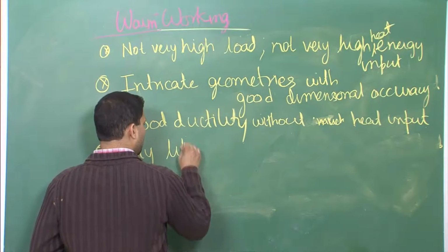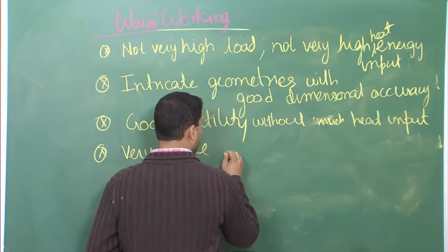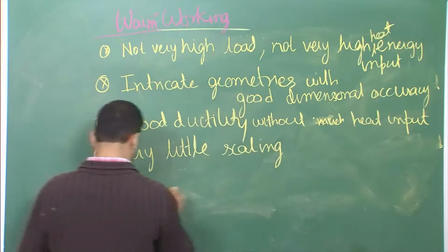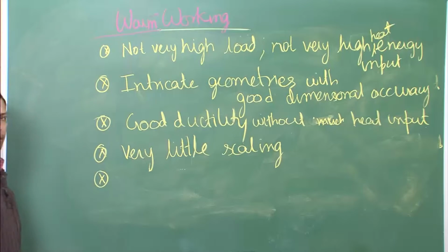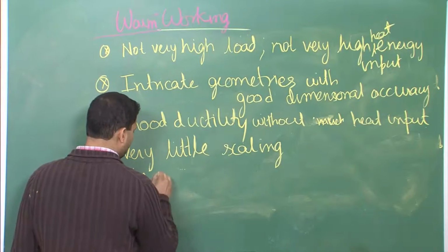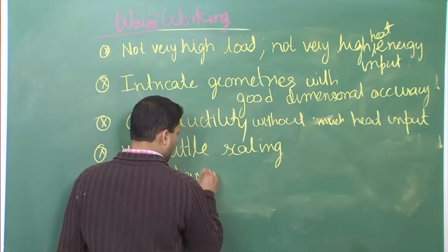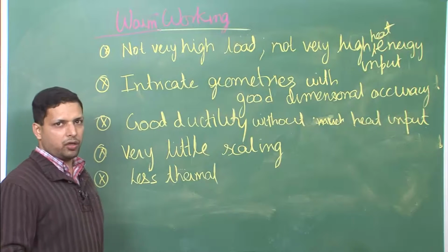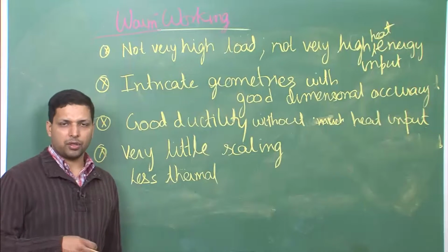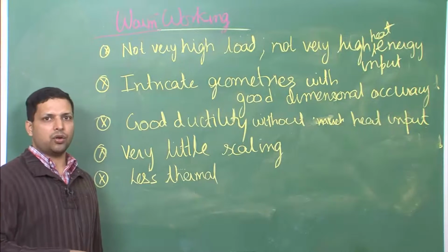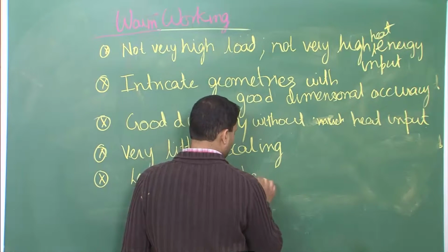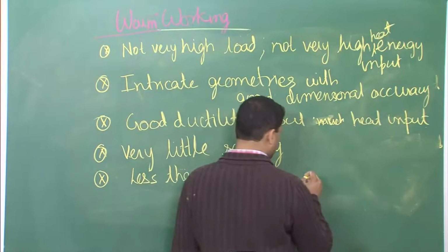So, although we are using relatively high temperature, since we are using a little less high temperature, there is less thermal shock to the tools. Remember, if you are working at high temperature, even your tools get exposed to those temperatures, and if you start from a cold temperature to a hot temperature and then again bring it down to low temperature, it is called thermal shock. So, less thermal shocks of those kind for tool materials.